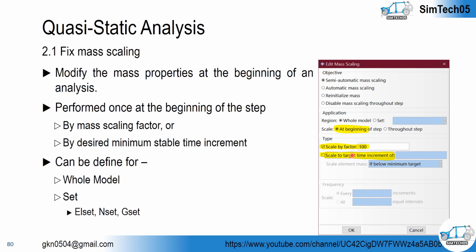It can be introduced by defining the mass factor manually, or we define the required increment size, and accordingly the software will define the mass scale factor and generate the new mass matrix that will be carried throughout the simulation. That can be defined for the whole model or a particular set.